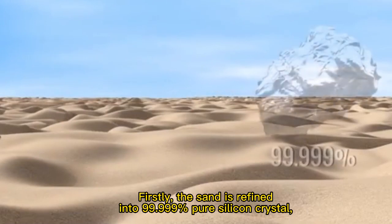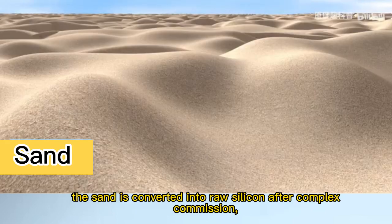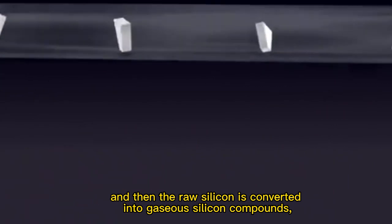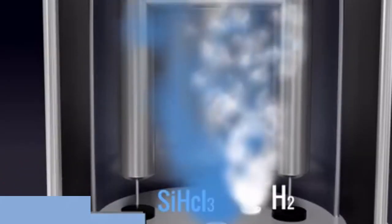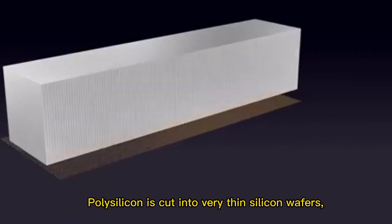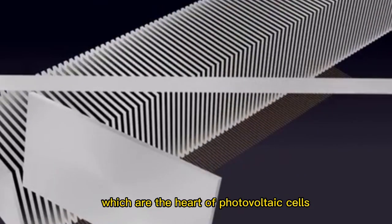Firstly, the sand is refined into 99.999% pure silicon crystal. The sand is converted into raw silicon after complex reactions. And then the raw silicon is converted into gaseous silicon compounds, and then mixed with hydrogen to obtain high-purity polysilicon. Polysilicon is cut into very thin silicon wafers, which are the heart of photovoltaic cells.